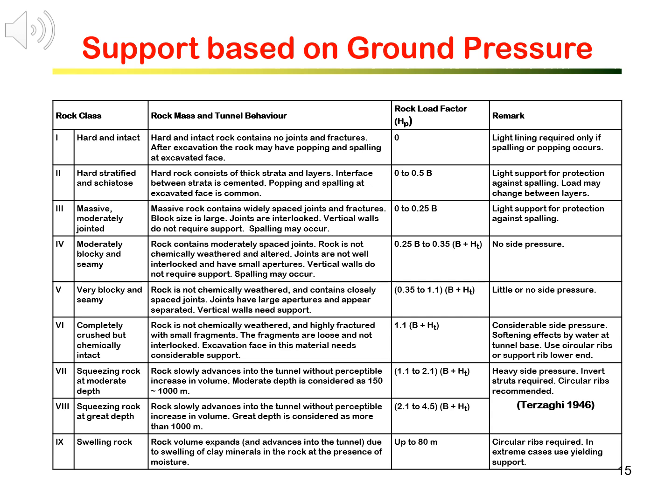What I wanted to highlight is the last 4 classes, from class 6 to 9. They deal with very highly fractured, squeezing, and swelling rocks, which are commonly found under the Alps. Rock load factor provides the method to estimate ground pressure to rock support in weak, poor, and sometimes highly stressed rock masses.